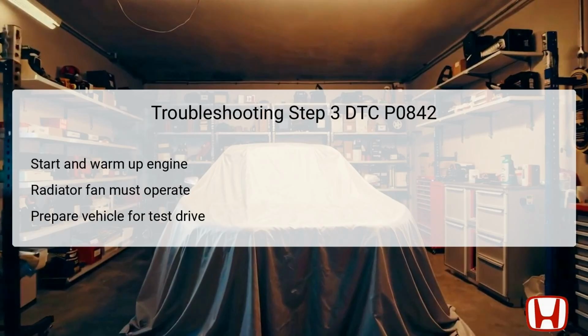In this troubleshooting step, the next action involves starting the engine and allowing it to warm up to its normal operating temperature. A clear indicator that the engine is warm enough is when the radiator fan engages, showcasing that the system is operating within expected temperature ranges. This warming process is crucial as it ensures that the transmission fluid also reaches optimal conditions for accurate testing.